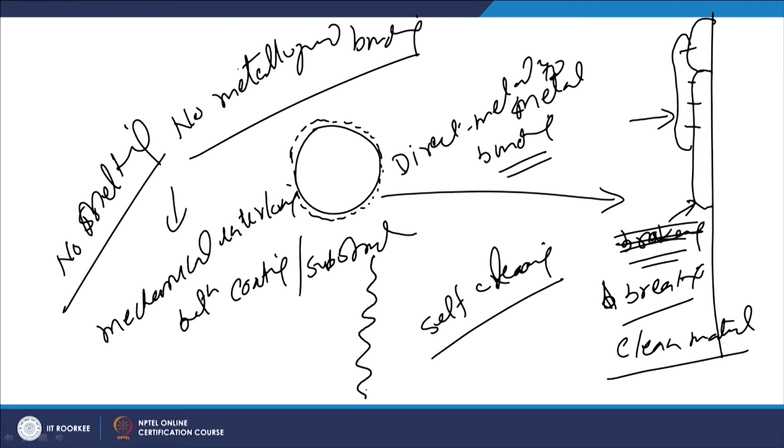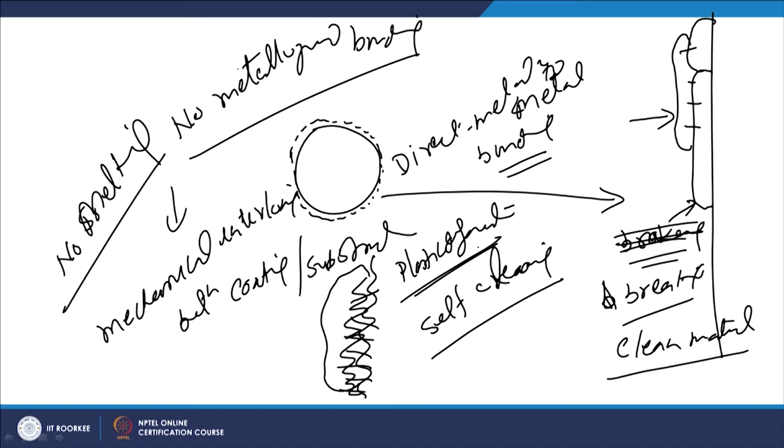That if the irregularities are present at the surface, then the particles will get flattened and deformed, means all these peaks and valleys will get deformed and get mechanically interlocked like this. So the presence of irregularities, at the same time the plastic deformation of these irregularities, is important for mechanical interlocking of the material which is being deposited.